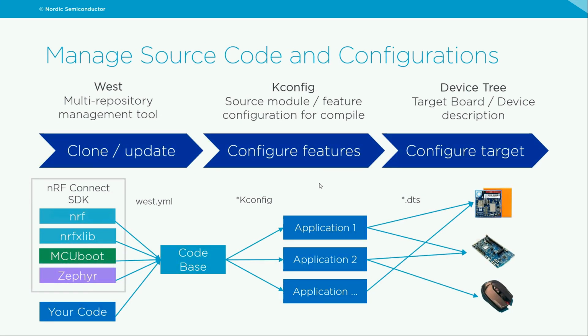So just a bit about managing source code and configurations. We do have, like I said, West, the multi-repository management tool. That's how you can clone and update. You can see on the figure below in the left-hand corner, you have the nRF Connect SDK with the 4 main repositories. And then you can add your own code outside of that. And that then becomes the code base. You have the west.yaml file there.